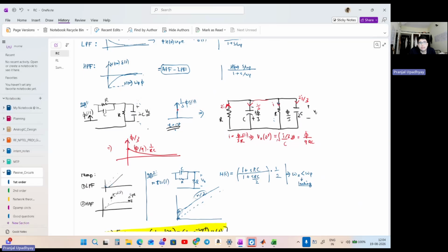So here again we have to use our brain, that since an impulse has been fed and that impulse is being divided capacitively through voltage division, the output also will have an impulse in this case. So this is something that we must realize, right? And when that impulse has vanished, what the dynamics in the circuit will be is also something that we must realize. After that sudden impulse, it won't decay from here, but that sudden impulse, which is now gone, will induce some currents in the resistors, and because of that, the value of the voltage at t equals to 0 plus will be something else, and then from there it will exponentially decay. So that's why this example is kind of important to understand.